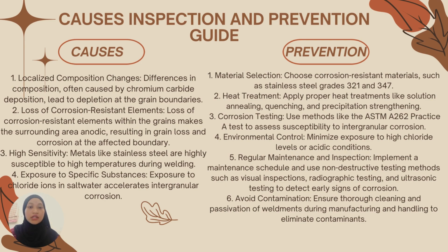In addition, the corrosion test is used as a method to evaluate the susceptibility to corrosion between the grains. And periodic maintenance and inspection is very important here. Non-destructive material tests such as visual inspection, radiographic tests, and ultrasonic tests are used to detect early signs of corrosion.